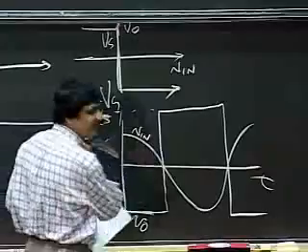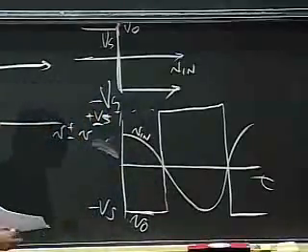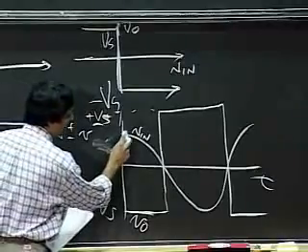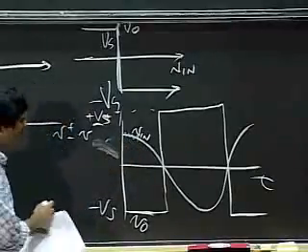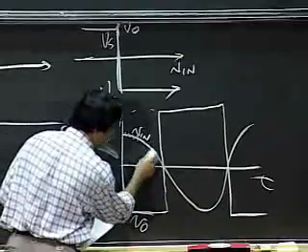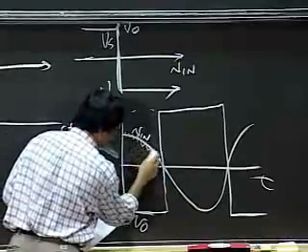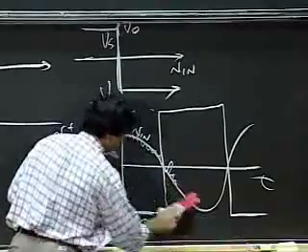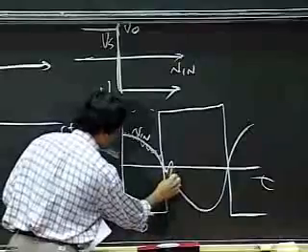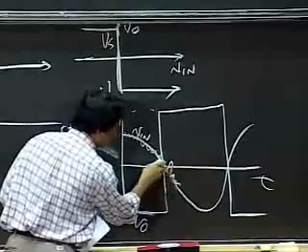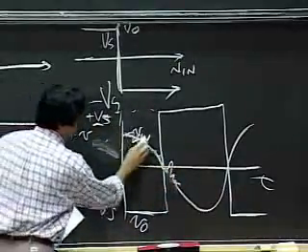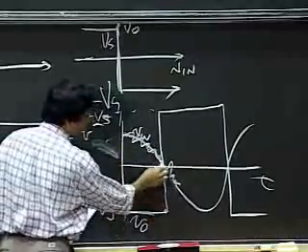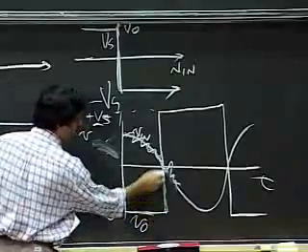Now, one problem with something like this is that this circuit can be quite messy in the following situation. Suppose I superimpose a small amount of noise on Vin, so I get a bunch of noise sitting on here. What happens is that at this point, where the value goes negative, I do bump up.